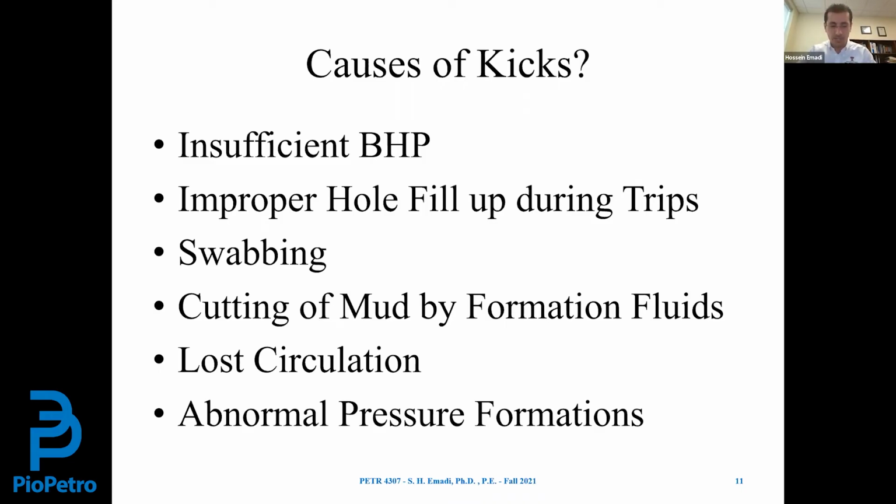kick happens. And as I mentioned previously, bottom pressure is not a constant value. When we are not pumping anything, bottom pressure is equal to static bottom pressure, hydrostatic pressure. When we start pumping, bottom pressure is equal to dynamic bottom pressure. When we increase the flow rate, bottom pressure increases. When we decrease the flow rate, bottom pressure decreases. So bottom pressure is not a fixed value. If at any point this pressure goes below formation pressure in a permeable formation, kick happens.